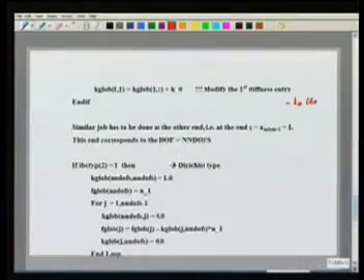Next, what do we do? Now we have to add the corresponding unknown u naught part to the stiffness side. So what do we do? Since we had the part minus k naught u naught, which is nothing but u1, I take it to the left hand side and I add k naught to the first diagonal term of the stiffness matrix, that takes care of the part due to the spring. Okay. So I have modified the stiffness part as well as load part in the case of a Robin boundary condition. Okay. Then I essentially end the application of boundary conditions for point 1.